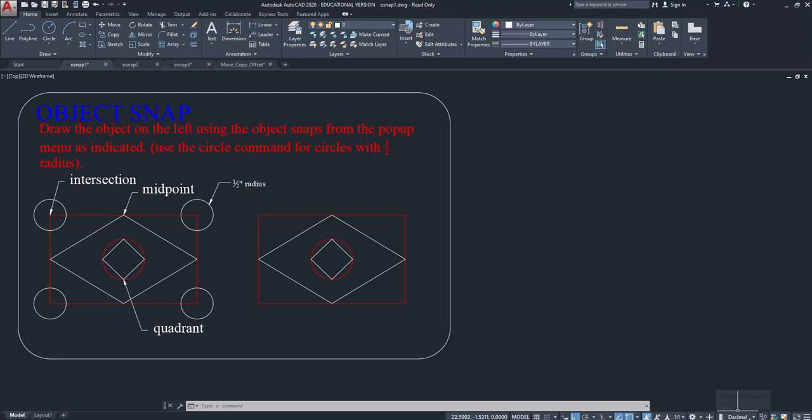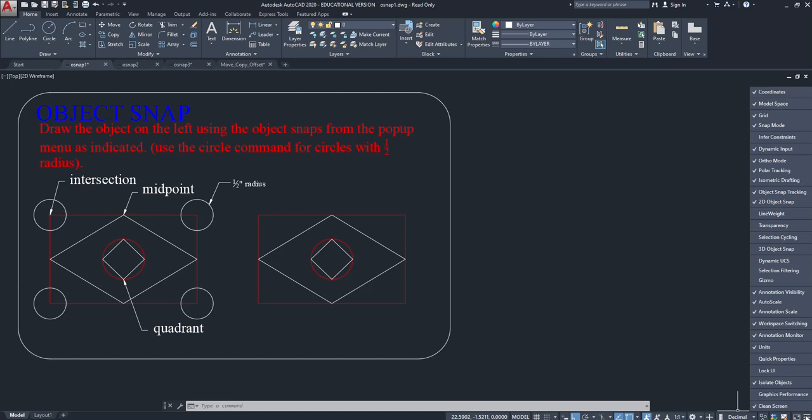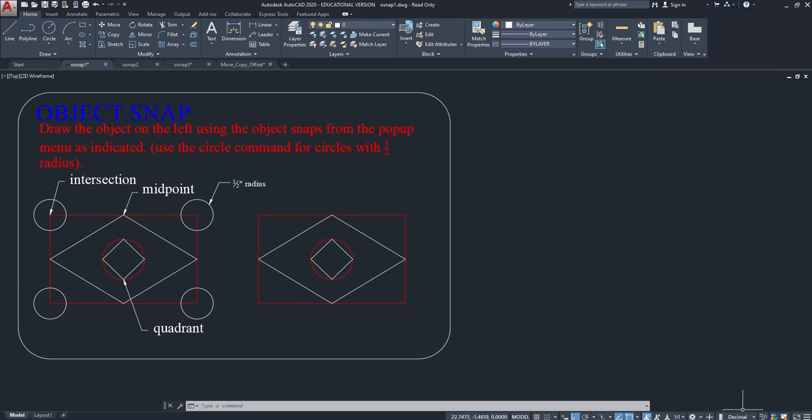If you can't see this, if you don't have something that says decimal right now, come over here to these 3 little lines, click, and you're going to turn on units. It may not be turned on your computer. With units turned on, this will show us visually what kind of units we're drawing in AutoCAD. In engineering, you're probably going to be using a lot of decimal type inputs, right? In architecture, you'll be using imperial units, right? For other applications, or if you're not drawing here in the US, or for engineering, metric, right?